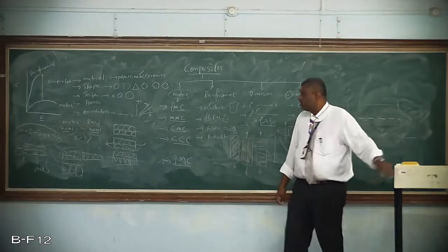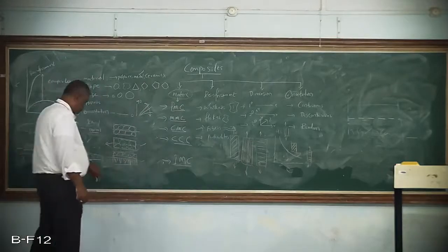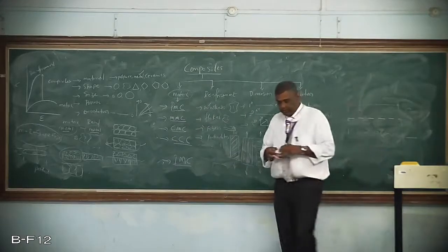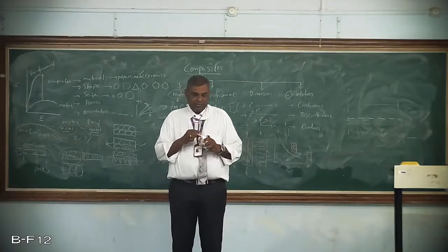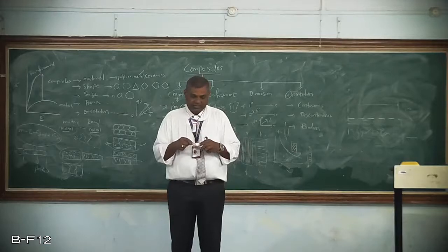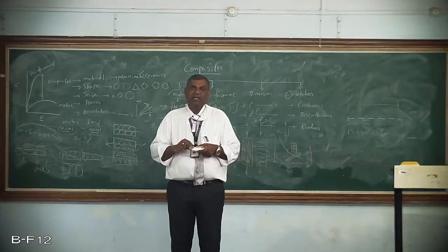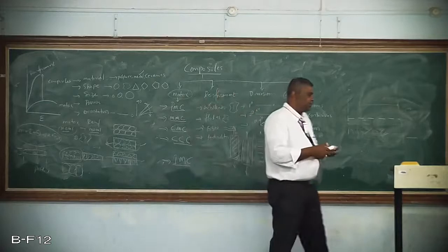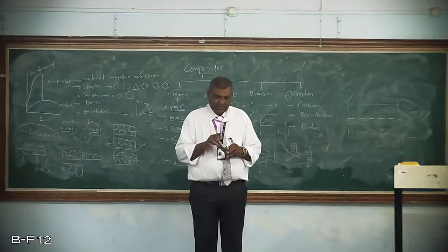Okay. So this is the general brief introduction that I have given you about composites. Now I am going to revise what we have discussed in today's class. From the beginning we have seen that a composite is a material which requires a minimum of two different materials, called matrix and reinforcement. Matrix materials have low properties: low strength, low density, everything is low. Whereas reinforcement materials have very high properties, but they are very costly and their processing is very difficult.